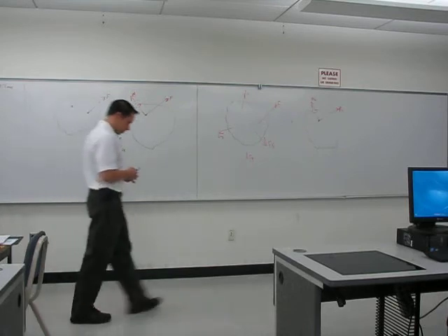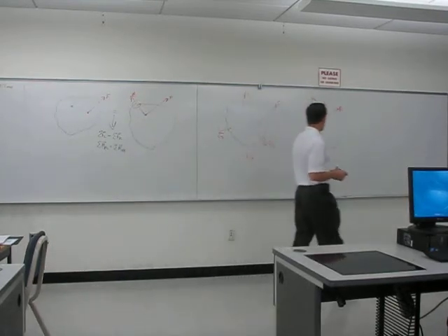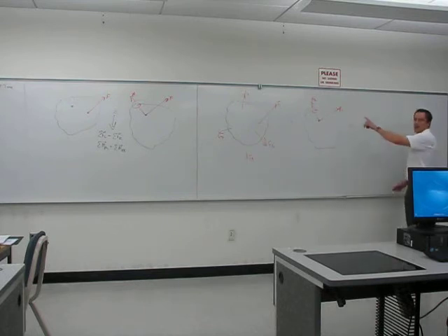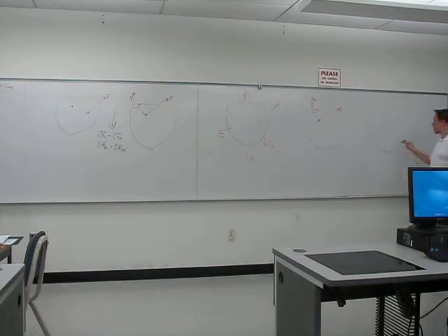And there's one other case that we might see as well. We can take this picture that's got the resultant force and the resultant moment vector, and we can find another point somewhere in the rigid body. Maybe it would be down here. And if we move the resultant force to this point, we're going to have to add another moment vector into the picture.